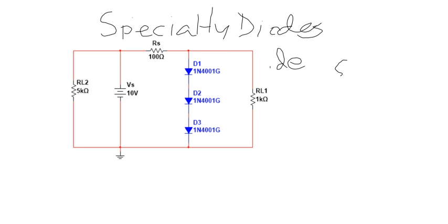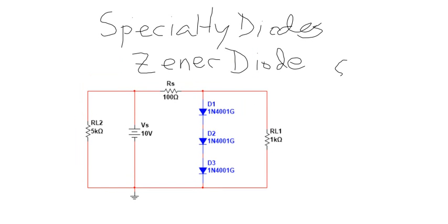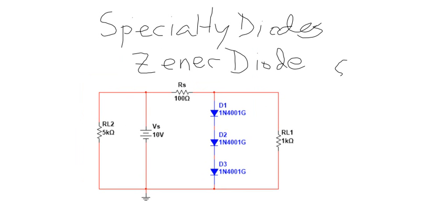Let's see, we had a circuit we looked at in a previous podcast. Let's see if I can dig it up. Here it is. Where we're using a stack of 3 diodes to lock in a voltage across our load resistor. If the diodes weren't there, we'd have a voltage divider. We'd work a current, and current times one resistor is its voltage, current times the other resistor is its voltage. Just a series circuit. But having the diodes there in parallel with this load resistor locks this resistor voltage into 3 times 7/10 of a volt, or 2.1 volts.